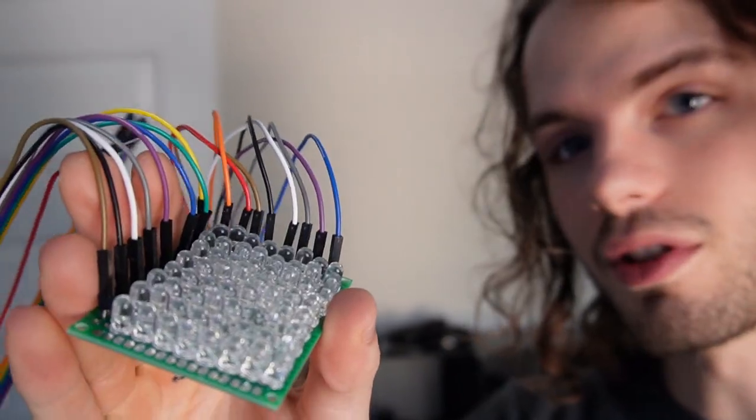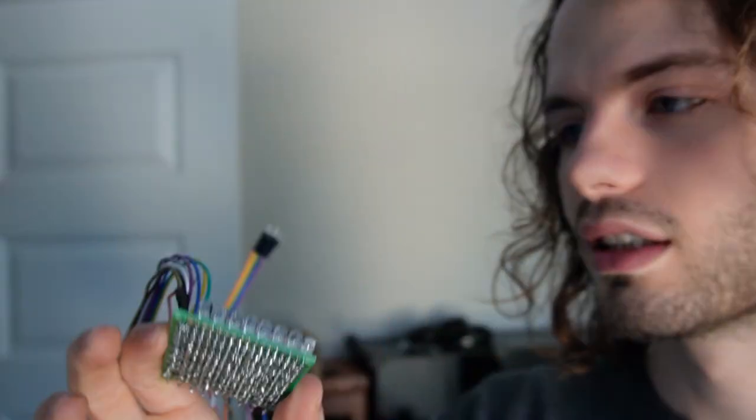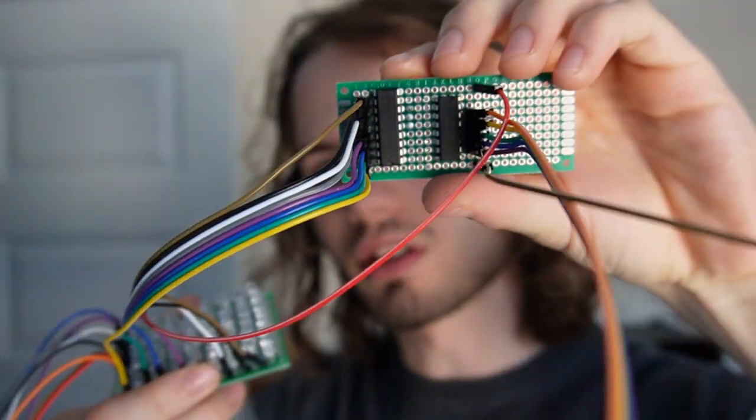So to give a little overview, we have the LED matrix here. I think I showed this earlier, but it's all soldered on the back. This feeds into the rows on this side. So the rows here are basically just a register and a Darlington array. And these are the control and power on here. And then on the other side are the columns. And here we have the register into the BJTs, resistors, all that.